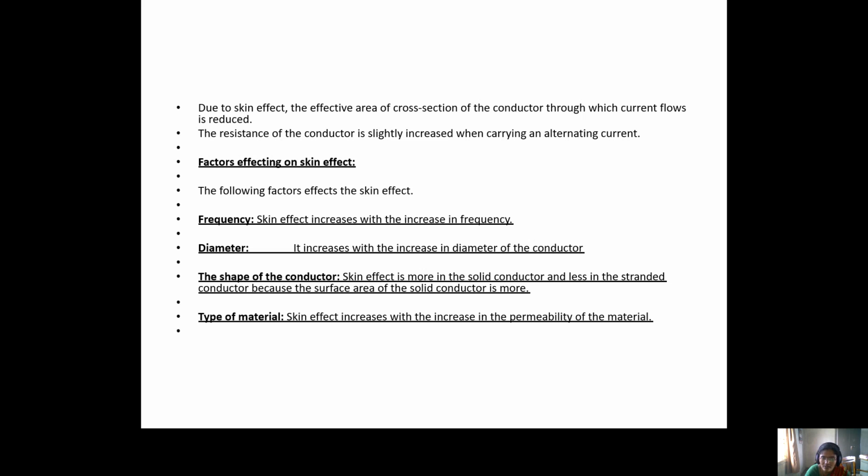Now we have to see what factors affect the skin effect. The following factors affect the skin effect: frequency, diameter, shape of the conductor, and type of material. First of all, frequency. Whenever frequency increases, the skin effect also increases. Skin effect increases with the increase in frequency. Next one is diameter.